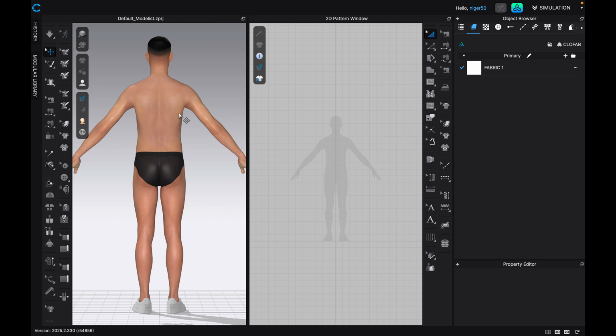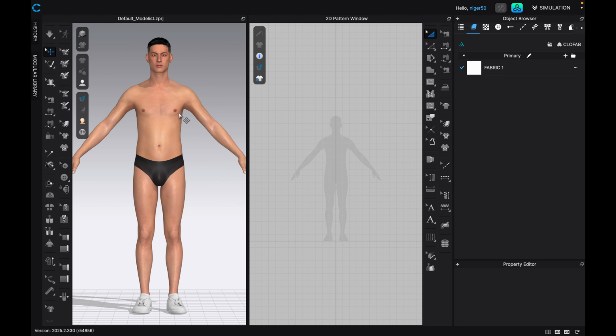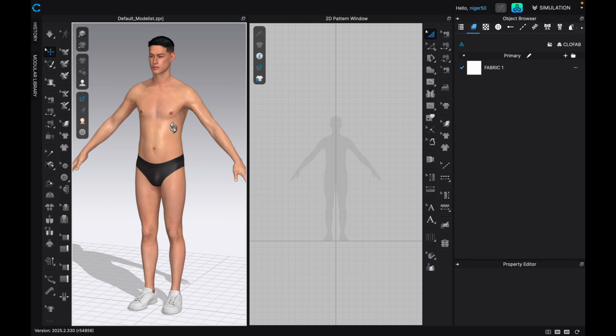You might also want to ask, is there any other way to pan around? The answer is yes. Apart from the 2, 4, 6, 8 on the keyboard, you can move around or you can pan around with your mouse. So if you want to use the mouse, that means you have to press the Option key first. Then you can left click to find your way around. If you're using a Windows computer, all you have to do is to hold the Alt key, left click and drag.